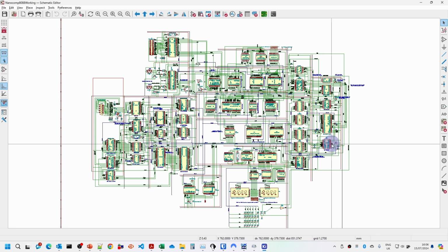I had a few questions about whether I can upload this onto GitHub. Unfortunately, some of the earlier updates, I think of KiCad 8, seem to have offset a lot of the components, so they're not actually matching on the 0.1 inch grid, so it kind of messes things up somewhat. And when you're changing the bus connections, after every 1 or 2 bus connection changes, it seems to crash the schematic editor, so it's taken quite a while to sort out. So I'm waiting until the next KiCad update. Hopefully we shall sort that issue out.